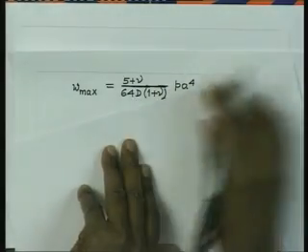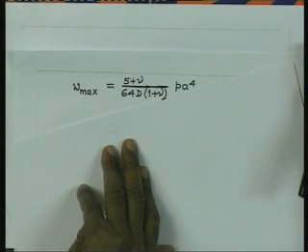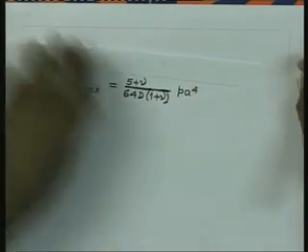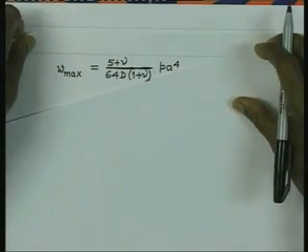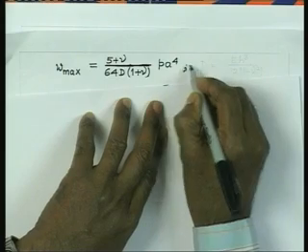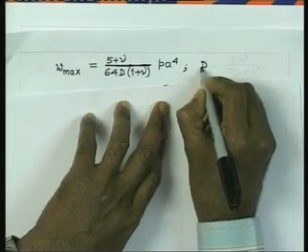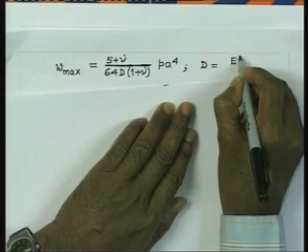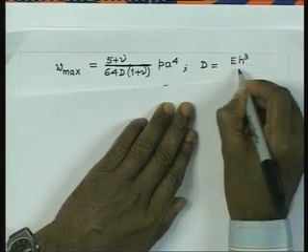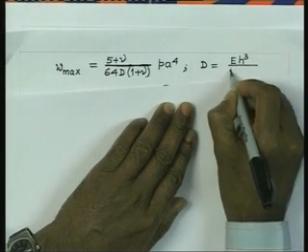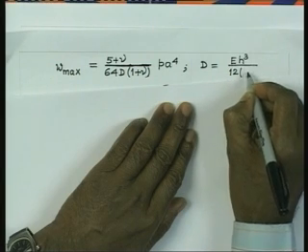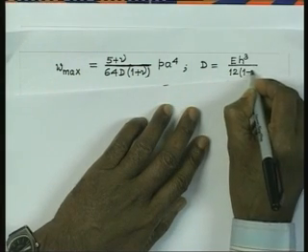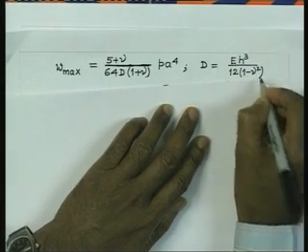This D is nothing but the flexural rigidity, and therefore, we should calculate this value; the rest of the values are all given. So, let us now calculate this D. D is nothing but E h cube by 12 into (1 minus nu square). So, it is different from that of a plate, and its value is E h cube by 12 into (1 minus nu square).